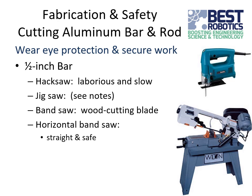Again, with these, make sure you're wearing eye protection and make sure you're securing your work. You don't want little bits of hot metal flying out and hitting you in the eye or anything. But yeah, you should be able to cut that. And aluminum in general is a really soft metal, so it's relatively forgiving and relatively easy to cut for being metal.